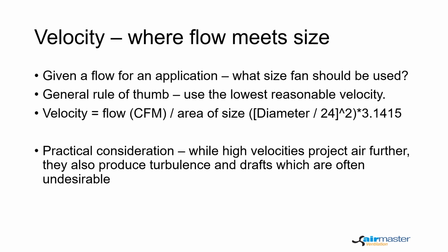With many things, higher velocity is better, but this is not necessarily true for panel fans. And we're going to show a couple of reasons why this is the case. But in general, all a higher velocity is going to achieve is turbulence and draft, which are not desirable for an air supply unit. And even for an exhaust unit, there's at least one good reason to avoid it as well. So select a fan with the lowest reasonable velocity.